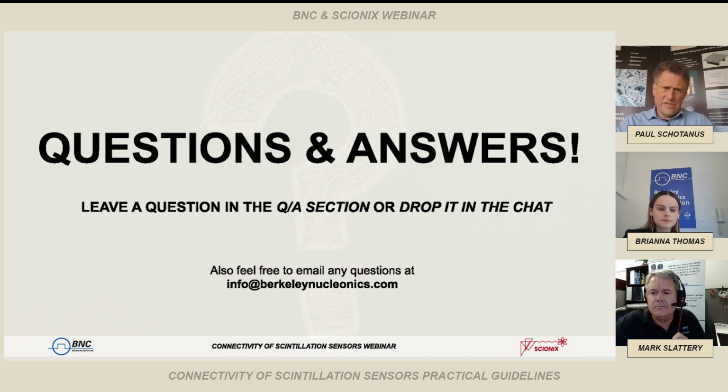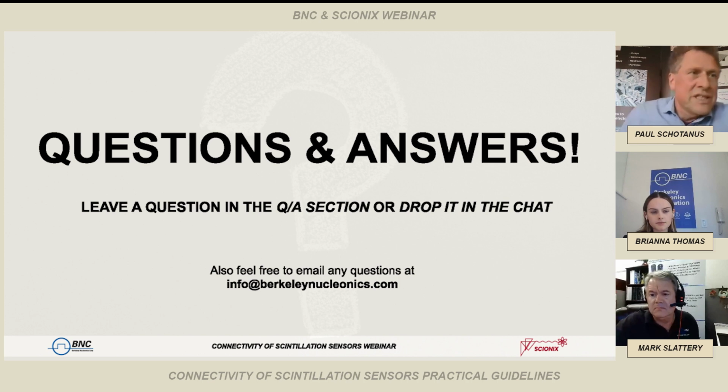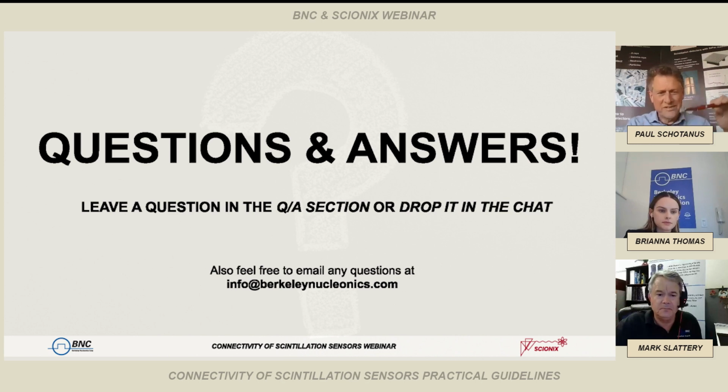Well, connectivity we have here defined as the way you connect your sensor to electronics. Of course, if you have a very small sensor, there is no room for lots of connectors. So if you have a very tiny sensor, something like the shape of a pen, and you want to connect this to your electronics, then there is not much room for a connector, so you have to use a flying leads cable with several cores. So of course, the size of your sensor influences your choice of how to connect it to something else. That is obvious, I would say, yes.